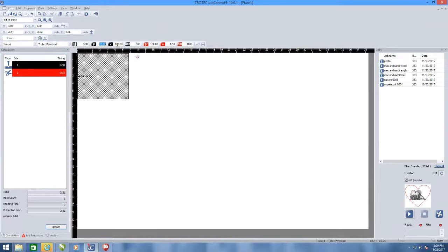If you're getting flaming, to me, that's a little bit too much power, unless you're using the mask. If you're using the mask, you're going to get a little bit of flaming because it's the mask that's flaming up. Again, I would never do photo engraving on glass unless I'm actually using the pre-mask. And if you want to learn a little bit more about that technique, I would suggest that you visit our YouTube channel and search for laser engraving photos on glass. It's in the training section playlist.